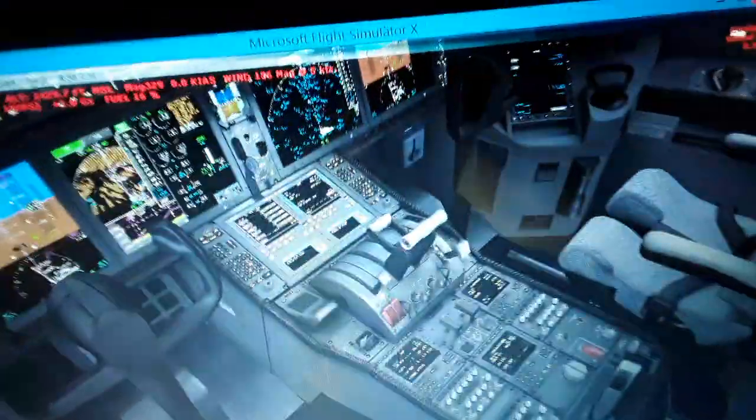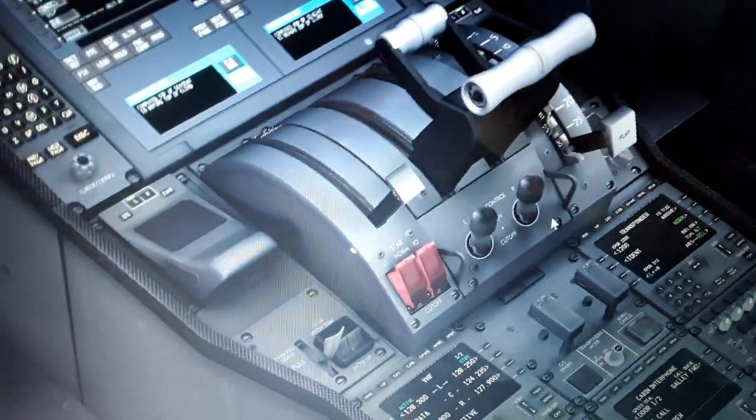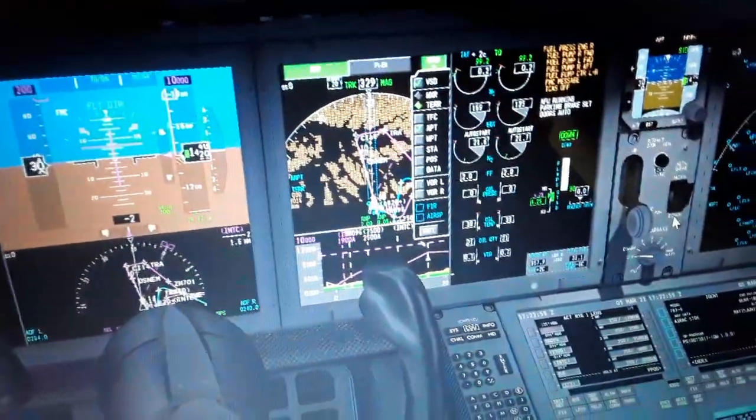There is a limit of pressurization from the APU, the auxiliary power unit. So we have only pressurization. We can start above 23% the fuel flow, and we have the auto start coming up.